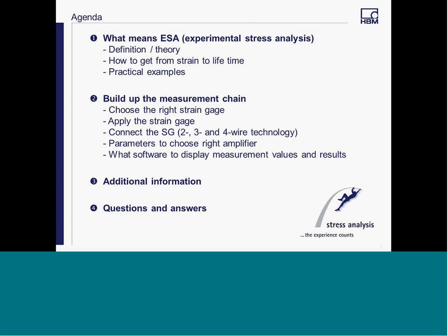After that, I want to come to the main topic, that is an explanation of building up a measurement chain. That means from the strain gauge, how to find the right strain gauge, how to apply the gauge, how to connect it, parameters to choose the right amplifiers, and last but not least about the software.